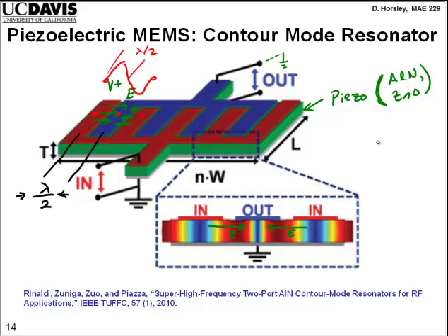So these electrodes are spaced by half an acoustic wavelength. This picture at the bottom that shows the nice rainbow pattern is the strain field, actually the displacement field inside this resonator. So you have basically 0 displacement within each electrode. One reason you want that is you don't want to stretch the electrodes, because there's loss associated with stretching these metal electrodes. So they are at 0 displacement points. There's maximal displacement in between the electrodes, like where I wrote E here.